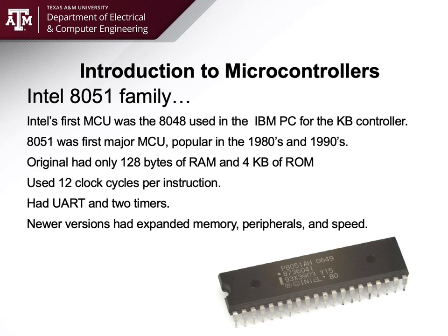So microcontrollers date back to the late 1970s and early 1980s. One of the very first microcontrollers was built specifically as a dedicated peripheral processor, where the IC itself did all of the functions and had all the RAM and all the ROM. We're not talking about a microprocessor solution, where you have a separate microprocessor, separate RAM, separate ROM, and separate interfaces, and the microprocessor is just the processing engine. A microcontroller is typically a one-chip solution, where all the peripherals, all the RAM, and all the ROM are built into one chip.